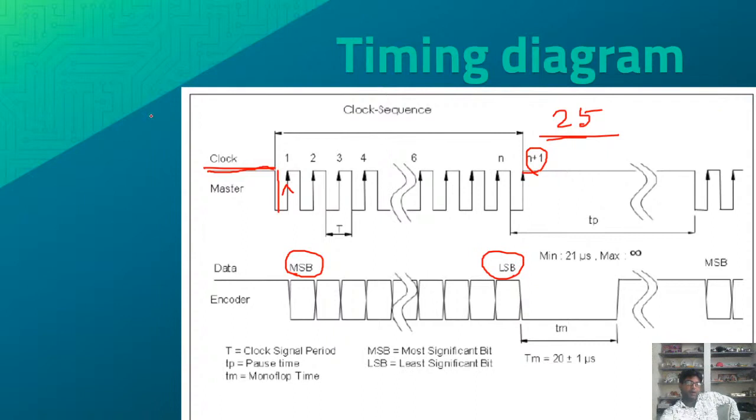For the encoder I have used, the minimum clock frequency is 50 kilohertz and the maximum clock frequency is, I think, 100 megahertz or something. I can't remember exactly, but it is something in a range like this. So the clock should be in between.